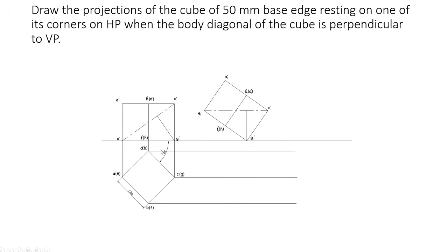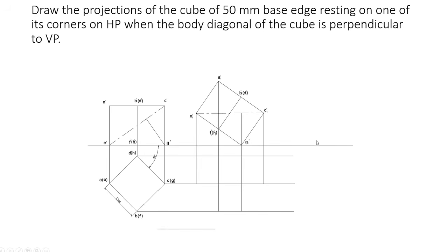Now next what you want to do, you just draw projection lines from here like this, parallel lines crossing this point. Okay, from all these 4 points, 1 2 3 4, this point and this point will be a common line, so you have only 3 lines parallel to the axis. Just draw parallel projection lines to the reference line.